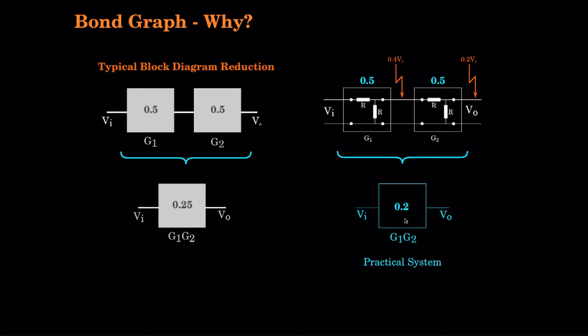Of course, for another system it will be another number, with different values of these R's. But we will always do our designs assuming that the input impedance is infinite and the output impedance is 0.